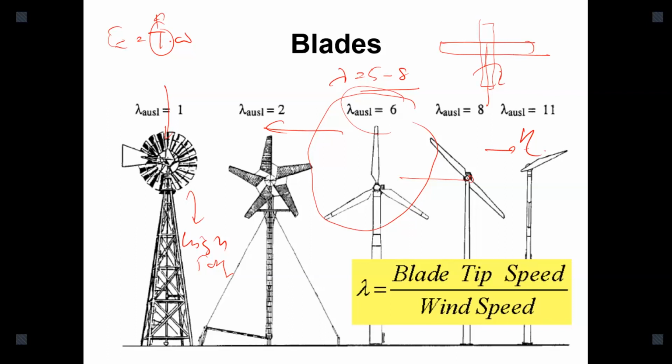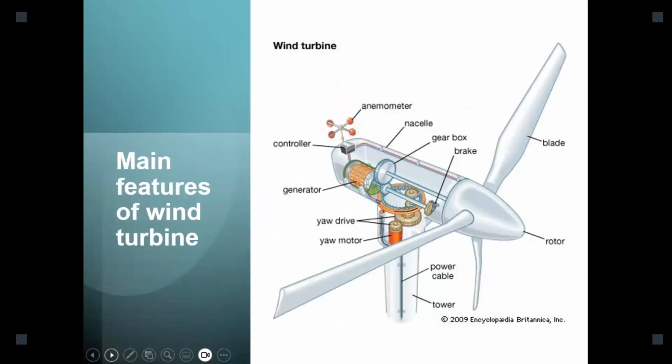The first one is the yawing problem. The second one is the balancing problem. That's the main reason people are using three-bladed ones. Large two-bladed wind rotors cannot yaw because of that issue: the rotating mass, the moment of inertia variation, the orientation of the wind rotor, the vertical position and the horizontal position. Okay, we can discuss these things quickly. The yawing concept is in my next few slides. As for the main features, I'm not going to discuss these things; I already discussed this in semester 1.